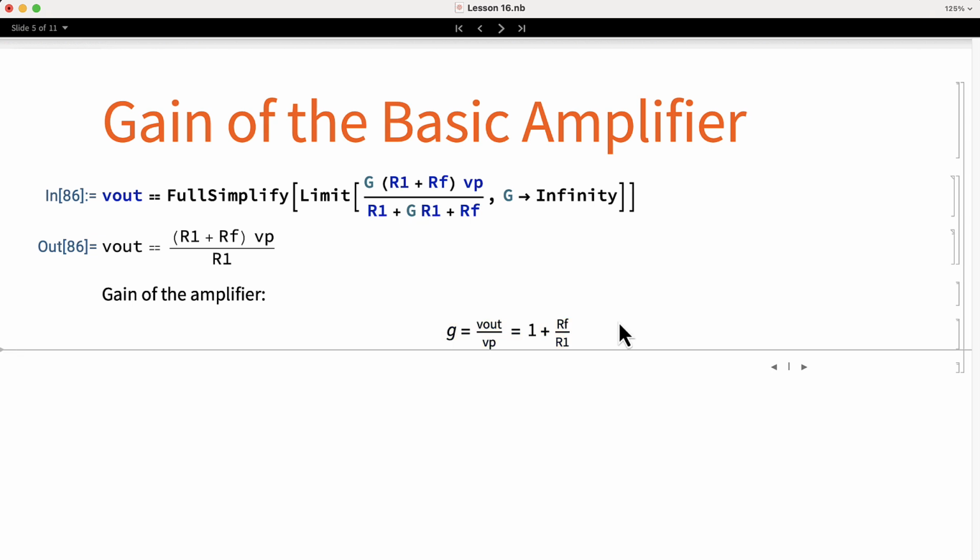Operational amplifiers are designed to have a very large gain. Some of the amplifiers I use have a value around 200,000x of amplification. For practical purposes, we can assume that the gain is infinite, and that will allow us to use the simplified formulas when calculating the values of a circuit. Let's put numeric values and see the results.